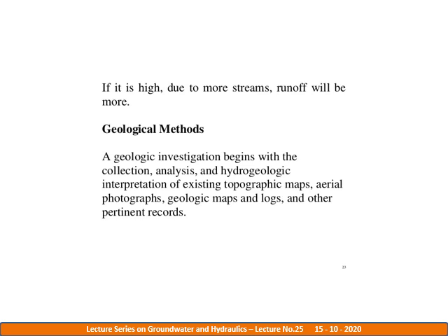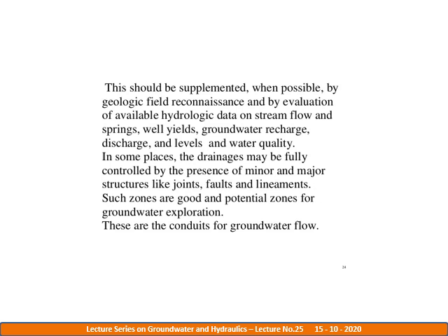Geological method. The geological investigation begins with the collection, analysis and hydrological interpretation of existing topographic maps, aerial photographs, geological maps and logs and other permanent records. This should be supplemented when possible by a geological field reconnaissance, recognizing the availability of hydrologic data on stream flow and springs, well yields, groundwater recharge, discharge and levels and water quantities.